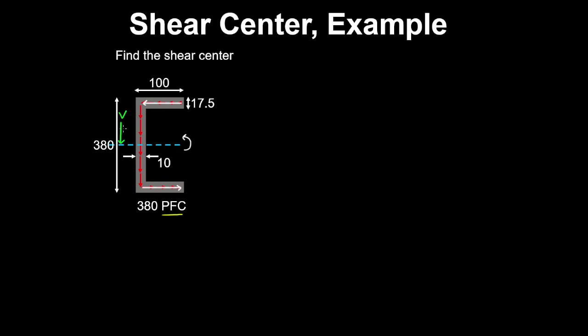then our guess is that the shear center is at some distance E to the left of the section. So the moment produced by the resultant force in the web counteracts that from the flange. Now to find the resultant force in a flange, we'll use calculus. So if we have some element of width dx,